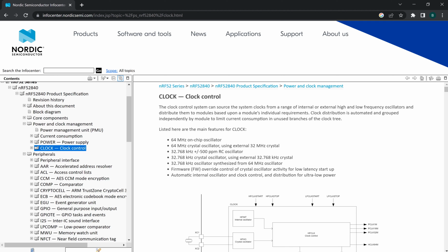Hello and welcome back to part 2 of writing an emulator for bare metal radio firmware. In the previous video we noticed that the firmware code accessed the status register of the clock peripheral and entered an endless loop. In this video we continue to model such peripherals to get our firmware to a correct state.